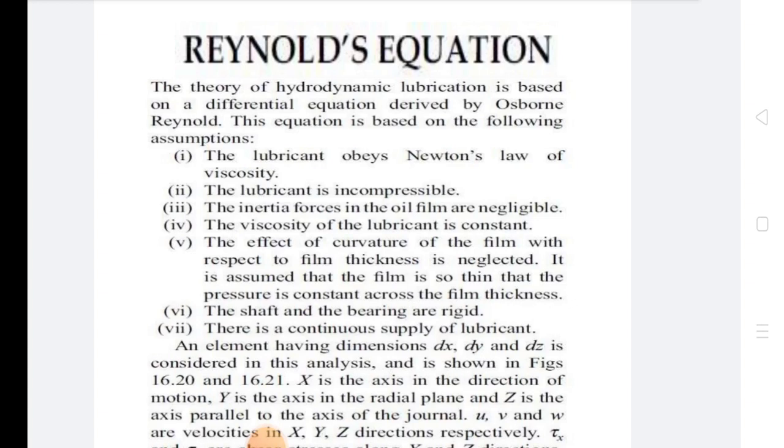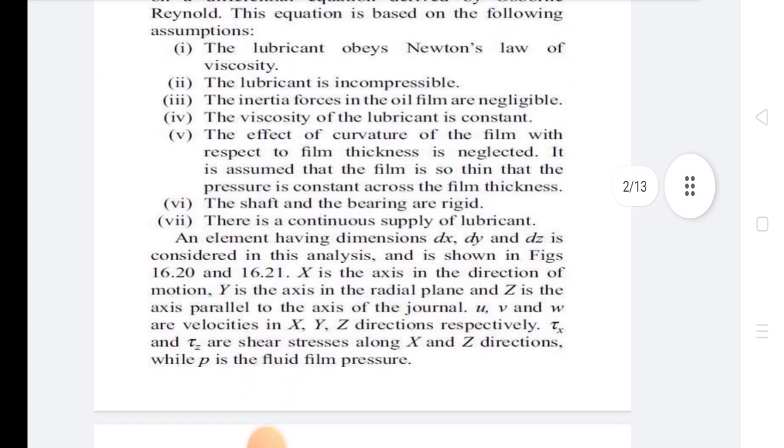The effect of curvature of the film with respect to film thickness is neglected. It is assumed that the film is so thin that the pressure is constant across the film thickness. The shaft and the bearing are rigid. There is continuous supply of lubricant.